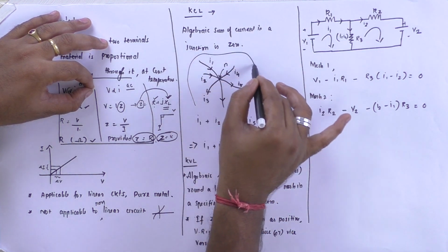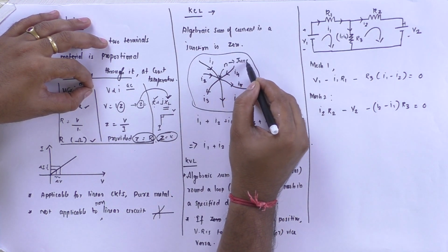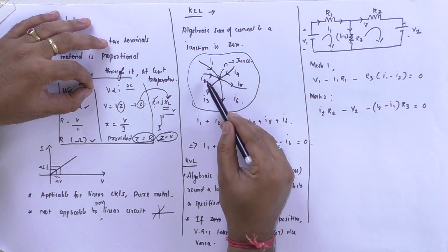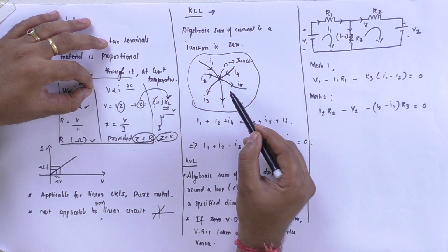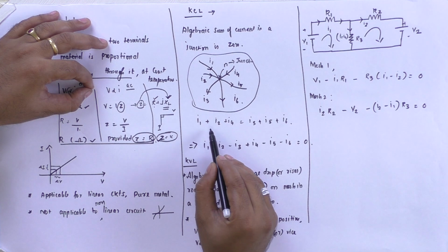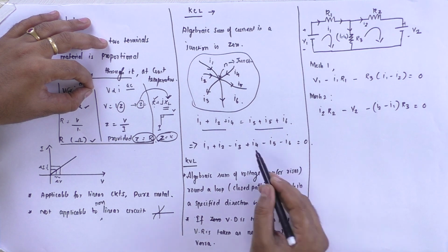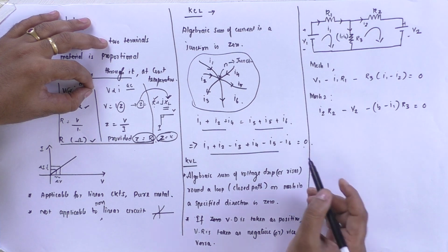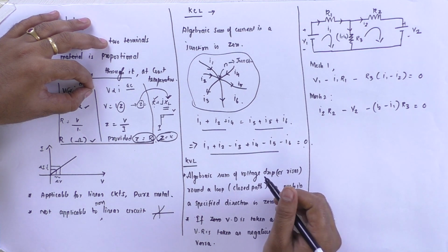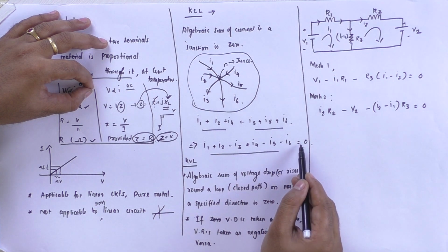So these are all simple branches that carry current, and N is represented as the junction. We can observe here the incoming direction of the current towards the junction, and the outgoing current is represented in the form of an arrow mark. So from the arrows, as per the statement, the current flowing towards the junction will be equal to the current flowing away from the junction. On equating, the equation terms to be equal to 0. This was the statement given by Kirchhoff in the current law, stating that the algebraic sum of the current flowing at the junction is equal to 0.